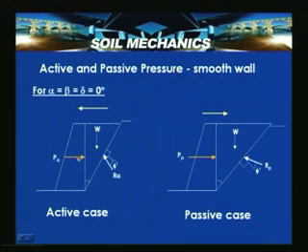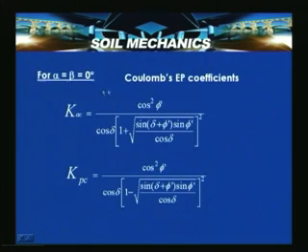So, PA, that is here it's horizontal, can be found out again by substituting this, and they change into the corresponding Rankine's coefficients. For a special case where alpha is equal to beta is equal to 0, but with delta wall interface, these are the Coulomb's earth pressure coefficients which are given here, and here phi dash is indicated as the drained interface friction angle, the drained friction angle.